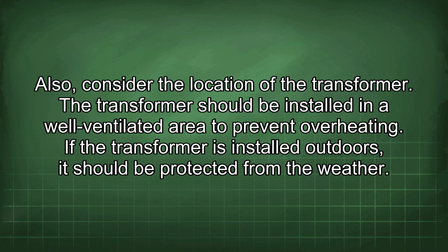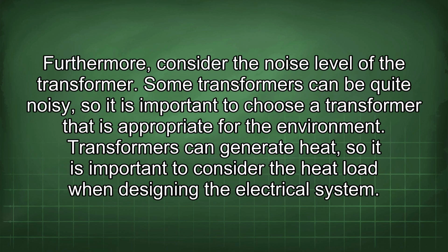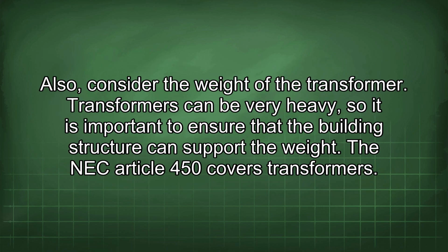If the transformer is installed outdoors, it should be protected from the weather. Furthermore, consider the noise level of the transformer. Some transformers can be quite noisy, so it is important to choose a transformer that is appropriate for the environment. Transformers can generate heat, so it is important to consider the heat load when designing the electrical system. Also, consider the weight of the transformer. Transformers can be very heavy, so it is important to ensure that the building structure can support the weight.